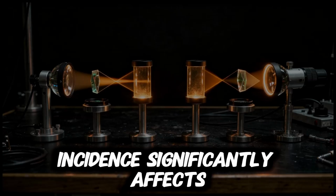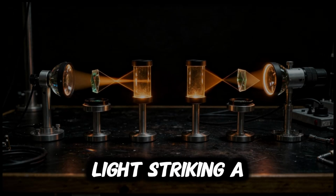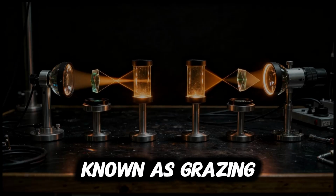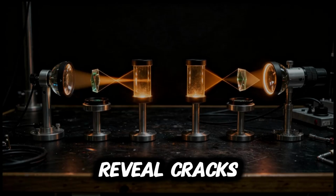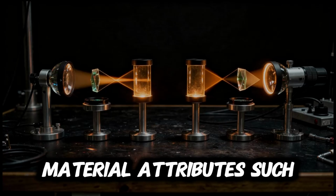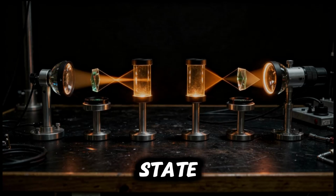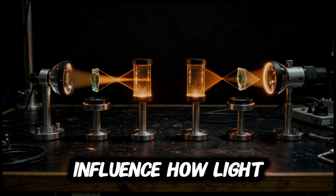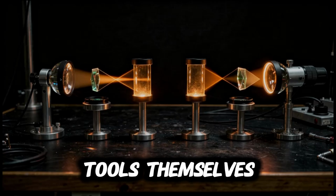The angle of incidence significantly affects defect visibility. Light striking a surface at a shallow angle, known as grazing incidence, casts shadows that reveal cracks, scratches, or uneven weld profiles. Material attributes such as reflectivity, surface roughness, oxidation state, and color directly influence how light interacts with the component. What about the tools themselves?